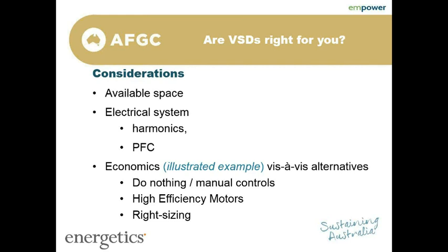The electrical system at site is something else also to look into, and it's mainly around whether there's power factor correction on your site. So variable speed drives effectively do power factor correction for the motor or whatever it's been installed on, just through that electronic control process.